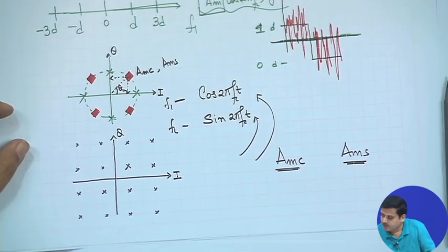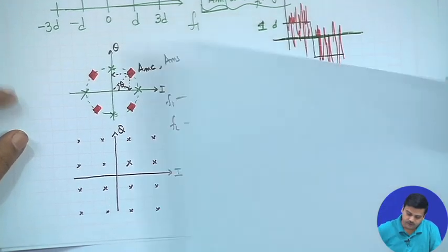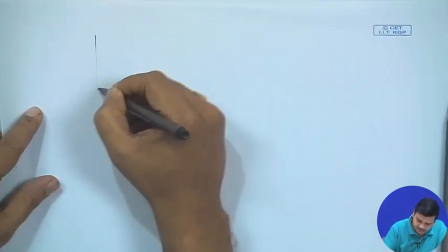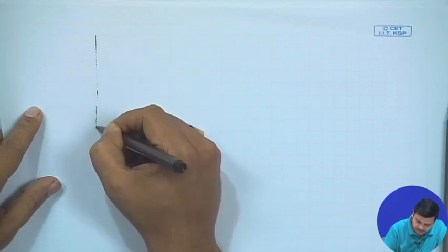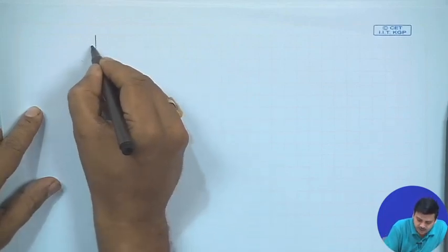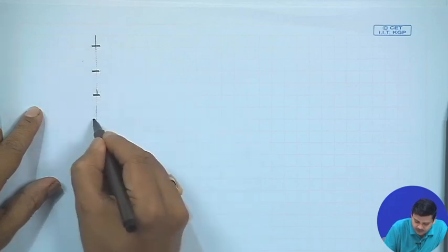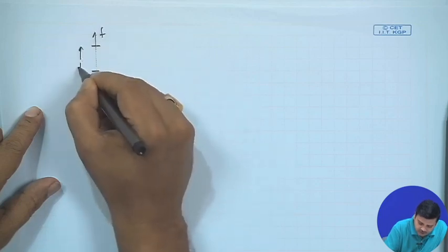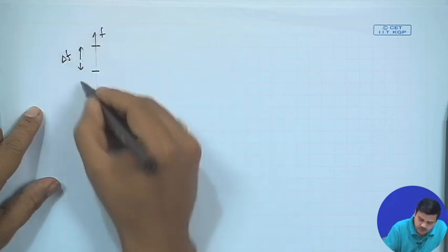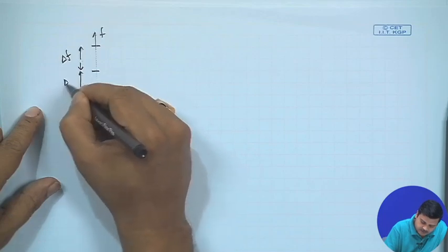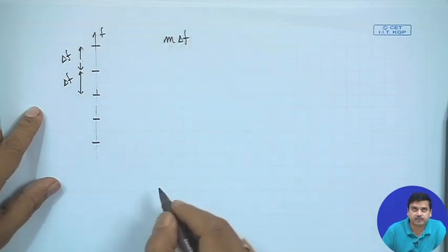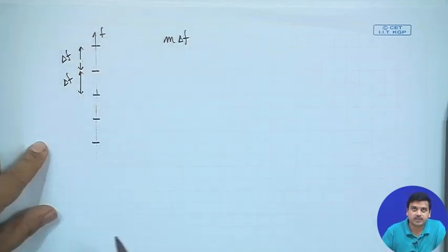From this point we moved further and we looked at n dimensional signaling. In the n dimensional signaling, we had a situation of selecting values of f where each of the channels were of bandwidth delta f, and one would select m times delta f in communicating which of these frequencies has been selected.